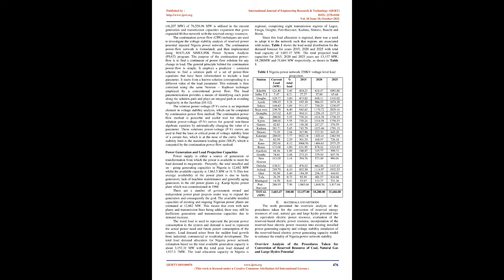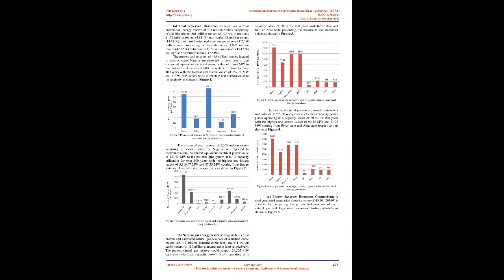The grid system in Nigeria is almost radial single circuit lines, fragile and very long transmission line. Many of these lines experience total or partial system collapse when subjected to major disturbance, and this makes voltage control difficult. Other problems include poor network configuration in some regional work centers, ineffective control of the transmission line parameters, large numbers of overloaded transformers in the grid systems, the use of transmission lines beyond their thermal limits, and frequent vandalism of 330 kV transmission lines in various parts of the country.